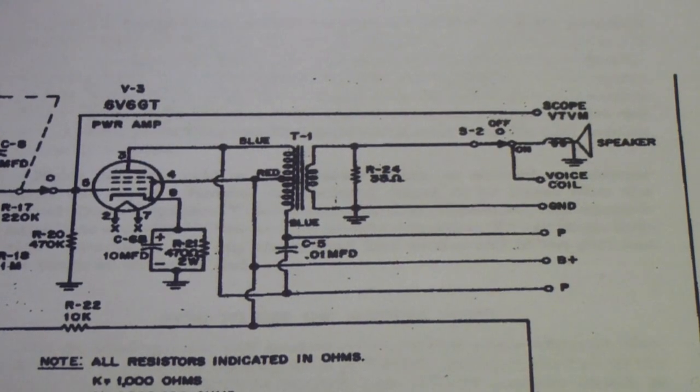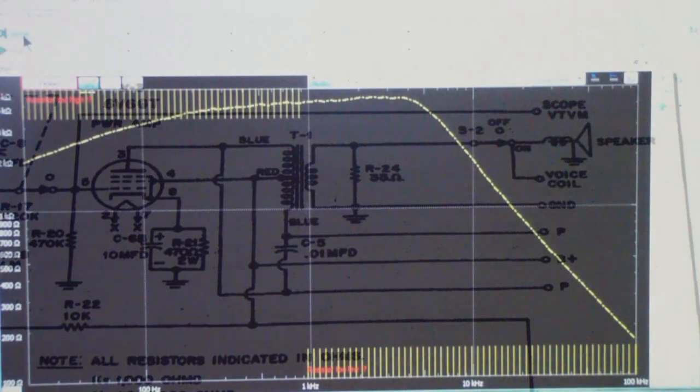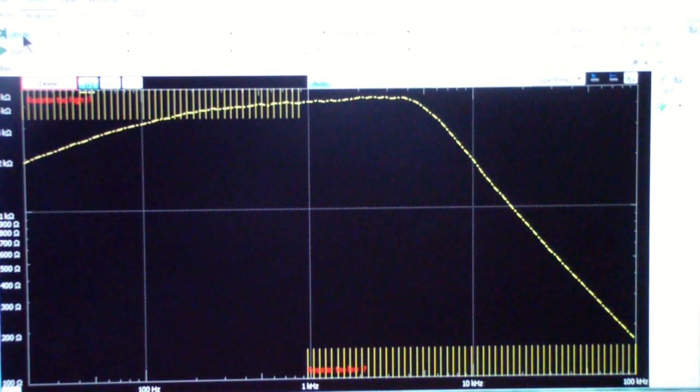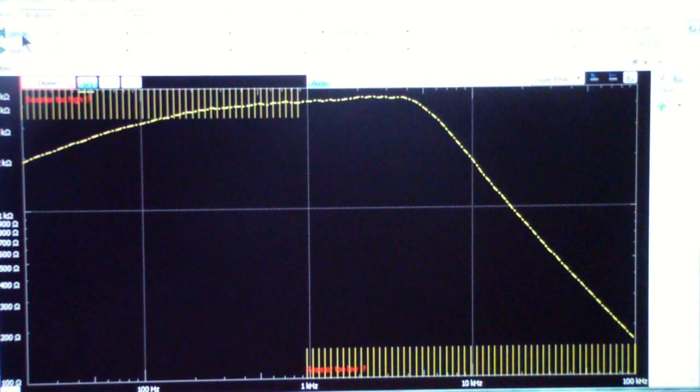So let's look at what the impedance analyzer shows. Well, my goodness, that doesn't look good, does it? The reason is that the resistor is incorrect for this output transformer. It has a lot more impedance in the primary because it's designed to match an output tube. And if you watched my other video on this, you know that generally output tubes need somewhere between 2 and 10K of impedance to work into to get a good match.